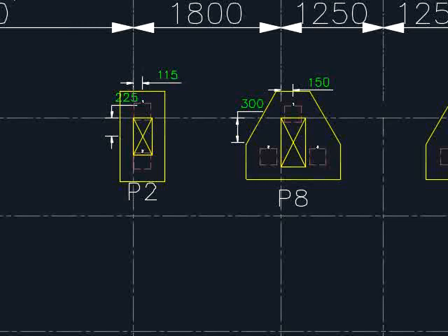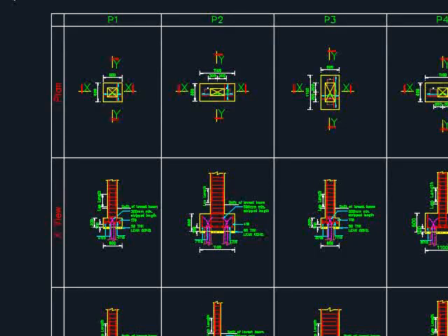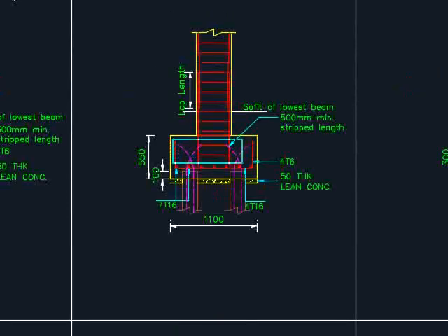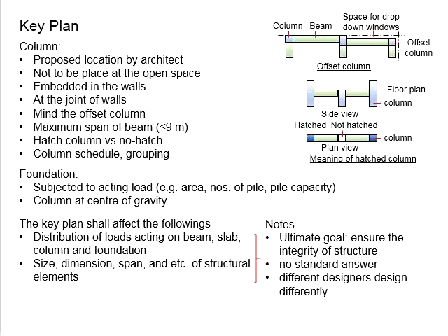You will need to provide details for the foundations, which will be reflected in the schedule of foundations. Provide the reinforcement bars, provide the dimensions, indicate the anchorage from the foundations, as well as the lapping lengths, and so on. This is about it regarding foundations.